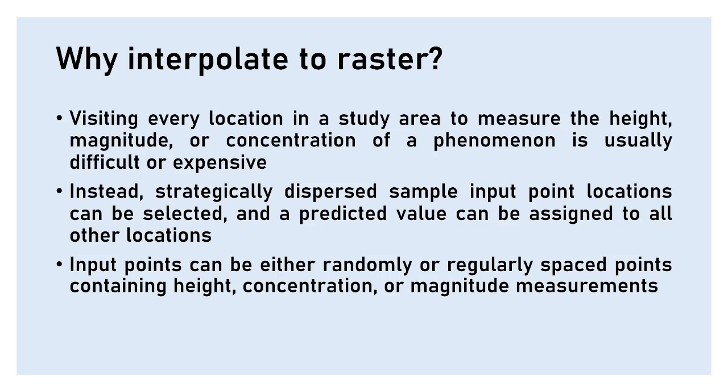It's not like we are considering data from one street, and the adjacent street is not very far away, and then we have another street which is really far away. This point can only account for this one. If you do the interpolation for that, it might not be very accurate. That's why I was saying strategic sampling is very much required for a proper interpolation.